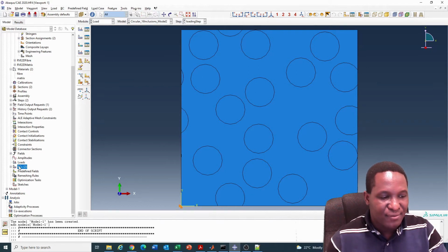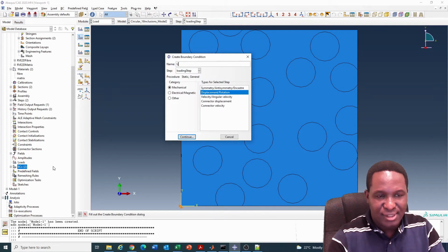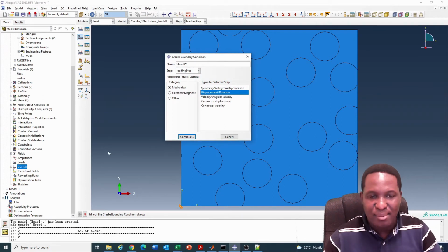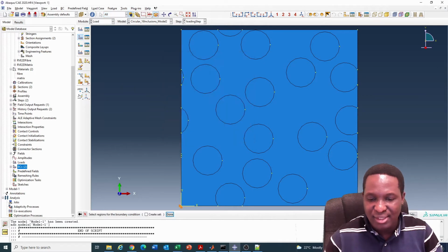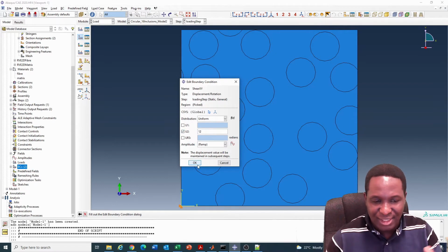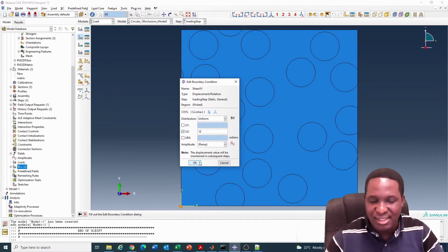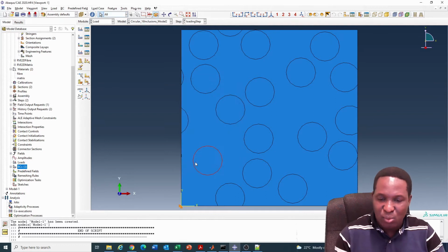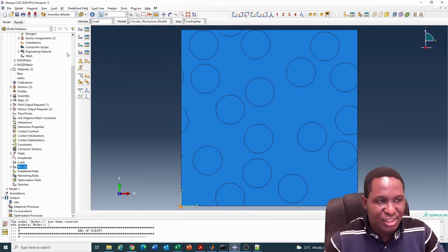Now we'll do the same for the shear. But we have to have two. So I'm going to call this shear in the XY direction, XY plane. So I'll pick that corner point and I'll use the same value of 12, but again, depending on the combination, you can keep changing this. This will be acting in the Y direction, one of the pure shear components.